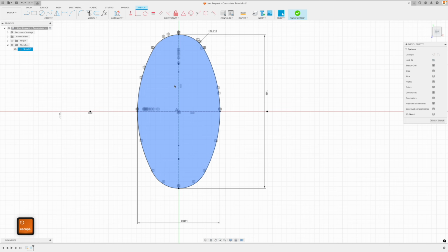Now they're locked together, but I want to make these mirrored or symmetrical. How do I do it? Let's go to symmetry. Click on that, hover our mouse, it tells us what to do. Select sketch objects. So sketch objects are the tangible sketch elements that we want to keep. They're not referenced. So I'm going to pick the point. Then I hover my mouse, it says select second sketch object. I'm going to click that, and then it asks for a symmetry line. And this is kind of the theoretical line, or it's not really that tangible. Again, it could be if we wanted it to, but we're just going to pick this x-axis right there.